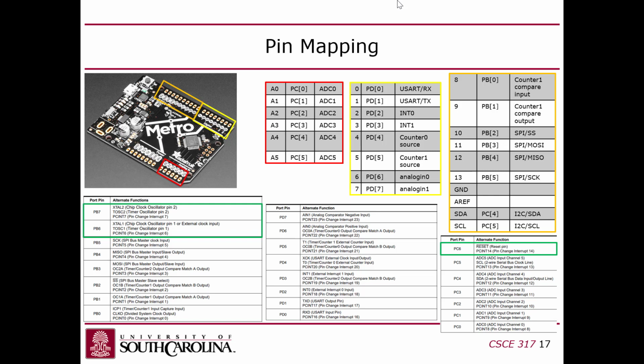I think they connected that button to PC6, port C bit 6. No, PC5 is ADC5, SCL, and PCINT13. So it's actually also an interrupt pin as well. And SDA is ADC4, SDA, and PCINT12. Yeah, so they're shorted. So some of these pins in the header are shorted to one another.